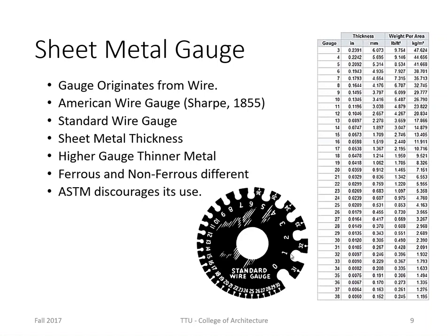This is a gauge tool, which allows you to check the gauge of a wire or a plate. The circular part, of course, is to test the wire. You run the wire through here, and that will tell you what gauge the wire is. And of course, the slot here is to gauge sheet metal. In other words, you can slide it over sheet metal. And you'll notice the gauges run from about a gauge 3.